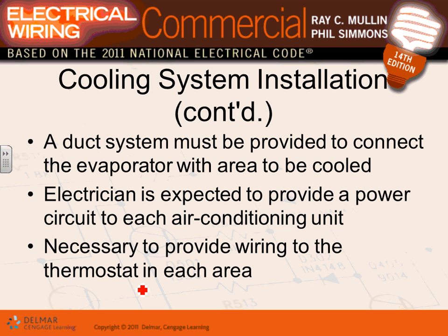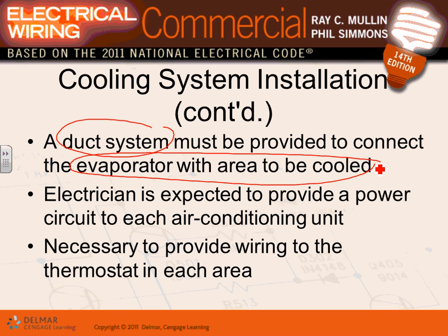Okay, if it's a split system, guys, or any other system, you need a duct system. So that's where our friends, the mechanical engineers, come in to connect the evaporator with the area to be cooled. You take that chilled air from the evaporator and you throw it with a fan. Well, there's a chilled refrigerant here. You throw the air right through it, guys, and pick the heat out of it. It becomes cold from the other end, and you have to circulate that cold air through your building.